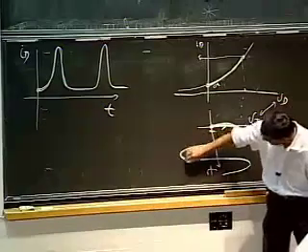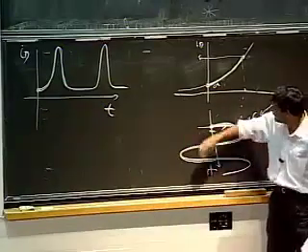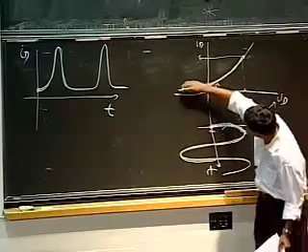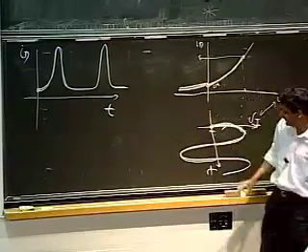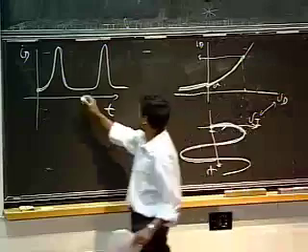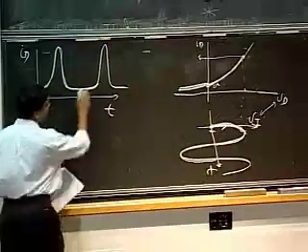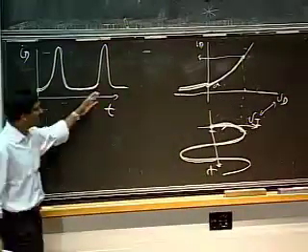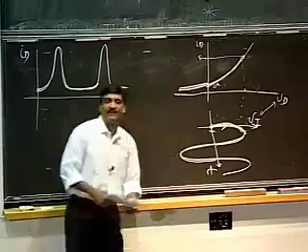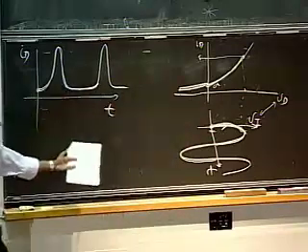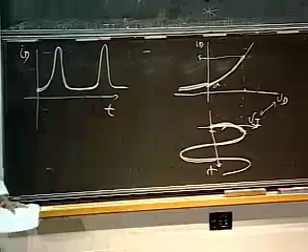And then for the whole negative excursion, notice that the whole negative excursion moves here. Okay, so for that entire negative excursion, I get an output that looks like this. Notice that this device has completely cut off and hammered negative going signals.